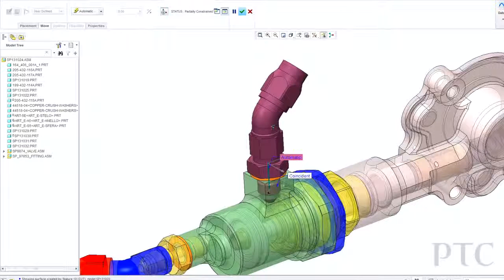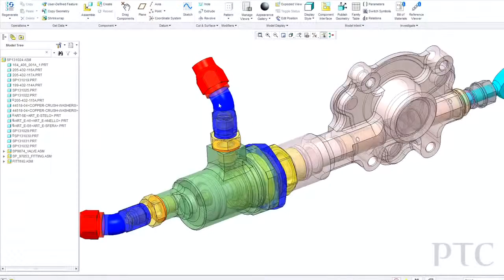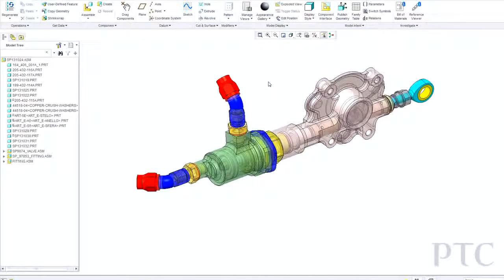And we'll automatically recognize, hey, you pick one cylindrical surface, you pick another, we've snapped to that. Then I just picked one planar surface. As soon as I drag up and down, because that's the only degree of freedom left, the system's smart enough then to snap at each surface that's within a certain tolerance vertically as that thing is assembled to that part. So it makes it nice for improving how easy it is to assemble components.